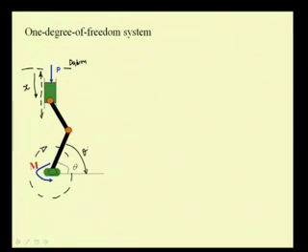So, for any displacement d theta of this link, the displacement dx is known. So, either by specifying theta or specifying x, I can completely define the configuration of this system. So, again this is a 1 degree of freedom system.